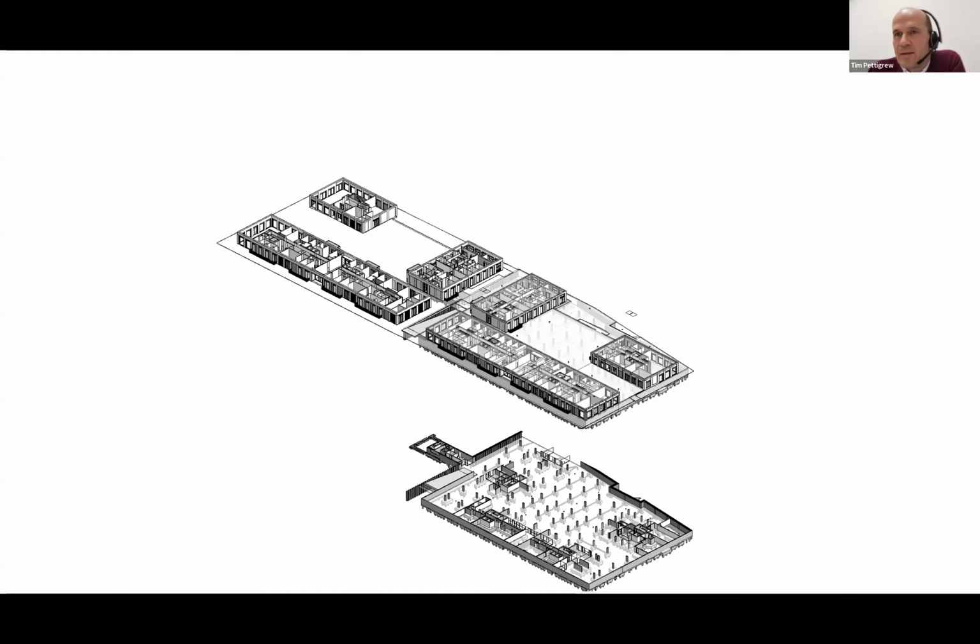One of the key things in MMC to me is getting a client's conviction at an earlier stage, committing to it, because the structural solutions that come out of the Builder system in particular, and every system that you use in the MMC is different, requires a different structural basement, different piling strategies, and different weight loads. So the Builder system is quite a heavy system along the facade, but it does take out a load of other weights from within the buildings because there are no columns.